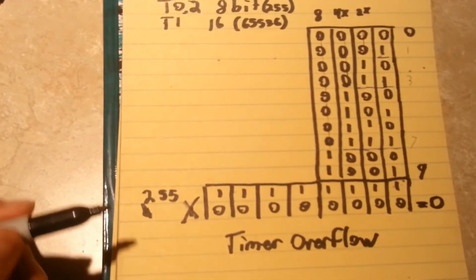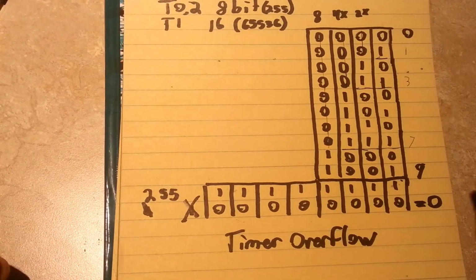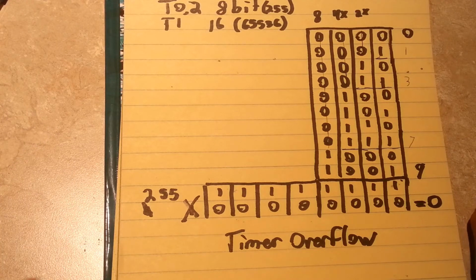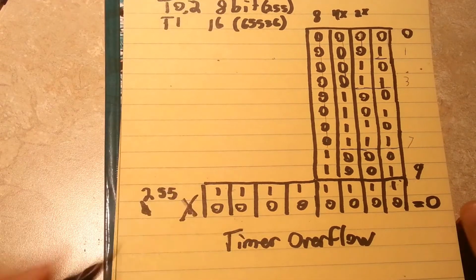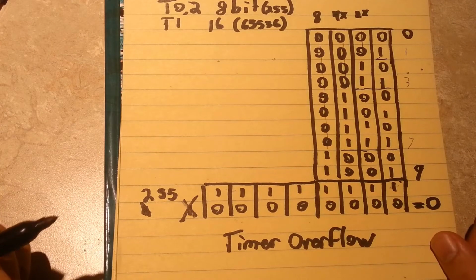You can configure your AVR to run an interrupt service routine on each timer overflow and create periodic events that occur exactly once every millisecond or something. This is also how Arduino implements the delay function and the millis function and the micros function using this timer counting. However, that's not how PWM is done. We're going to have to dig a little deeper.